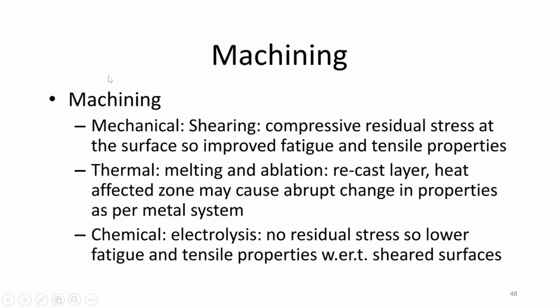Okay, so in case of machining, you can have chemical, in this case electrolysis, so there will be no residual stress. If you are removing only a small layer from the top of your material using chemical electrolysis, then there won't be any residual stresses formed. So lower fatigue properties and tensile properties will be there with respect to sheared surfaces, because there you were getting better properties due to compressive residual stresses.